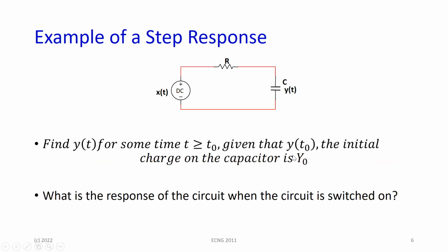Right? So let's look at, for instance, a simple thing. Here is a simple RC circuit that you met in physics. And you ask something now, so we're doing a step response. So here you have a DC supply, you have a simple resistor and capacitor, and you're now monitoring the voltage at this. You assume that the capacitor has 0. We have a DC source here, and we switch the circuit on. And we said last time that when you switch the circuit on, that is the equivalent of putting a unit step onto the system. So you switch that, what happens to the voltage across here?